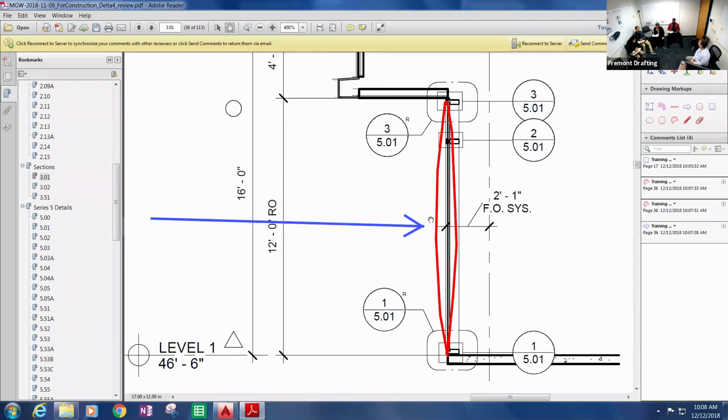The shapes and the red lines, that's going to be the mullion deflection that we're going to see. The specifications give us the criteria for that. Our normal deflection criteria is L over 175, where L is the length. So if you ever see an L over 175, the little L is the length. And then they'll also stipulate a lot of times 3/4 of an inch max.